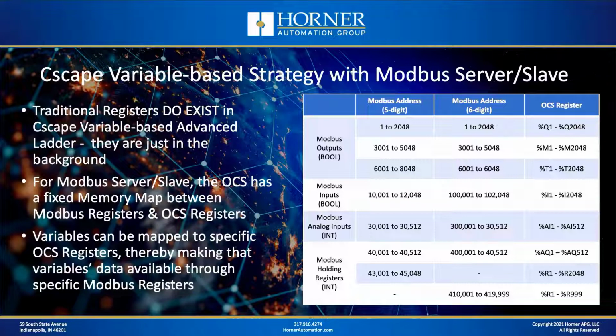Where it does matter is when you are using real-world I/O, inputs, outputs, analog outputs that are wired to specific terminal points on the terminal strip. They have specific memory addresses that you need to be concerned about. But when you're just creating regular variables, that's not a factor.